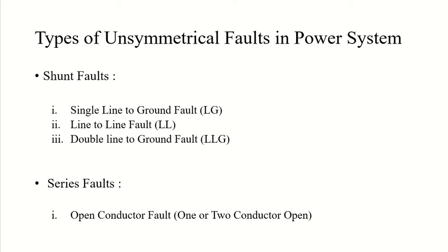The three-phase faults are analyzed to find the rupturing capacity of your circuit breaker. The unsymmetrical faults which we discussed here are very frequent in a power system, they are not rare. The three-phase short circuit faults are very rare. Sometimes it is possible that in some situations the fault current of a line to ground fault can surpass the three-phase fault as well.